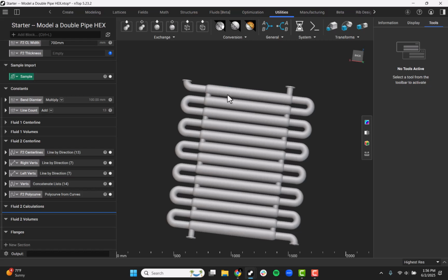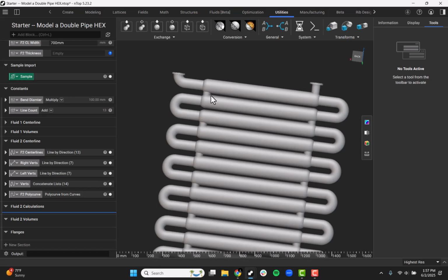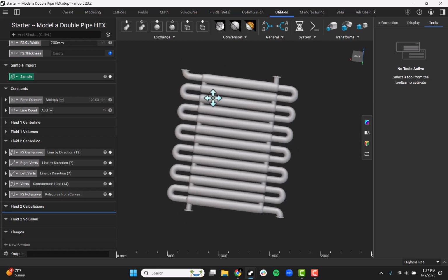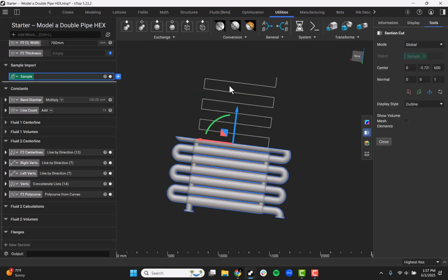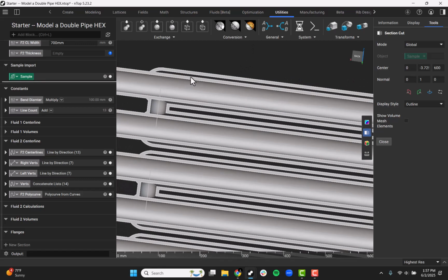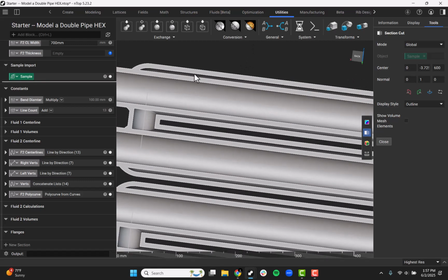To do this, we're going to use some cross-sectional area calculations, so we can have an equivalent cross-sectional area through our verticals, just as we do through our part. So we can have more even fluid flow throughout. If I take a section cut of this, we're going to take the inner radius here, and then the outer radius of our fluid.